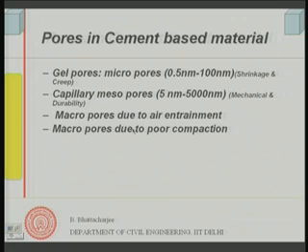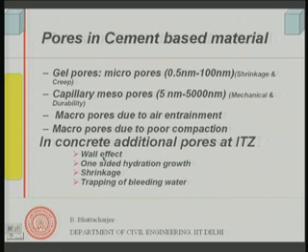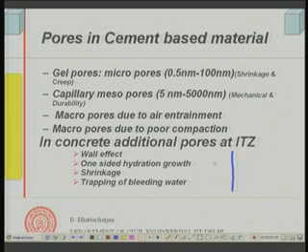Now, these pores can be present in paste also, but in concrete additionally you will have pores in the interfacial transition zones. And one effect I mentioned was wall effect, that is packing near the aggregate. This is aggregate, and the cement particles are fine, and packing cannot be very good close to the wall.